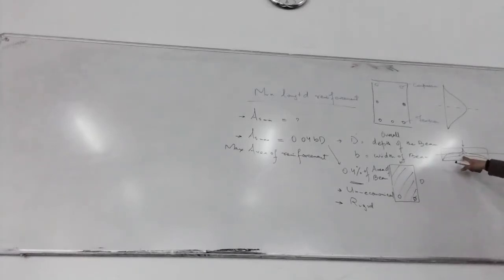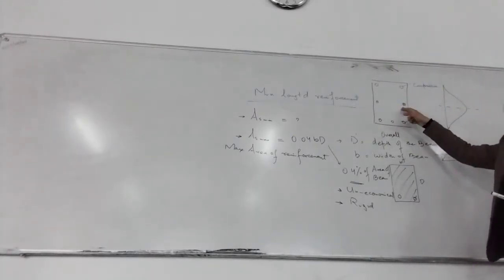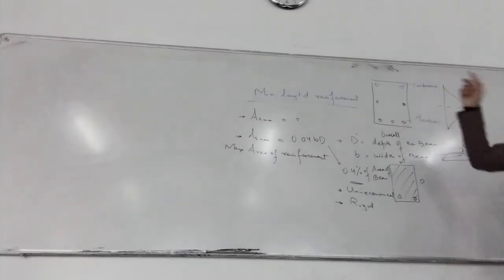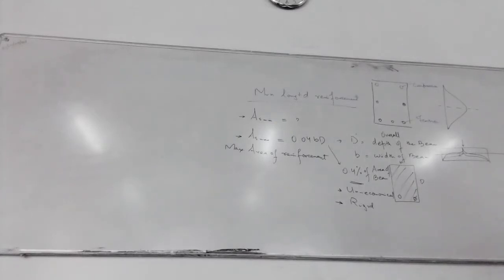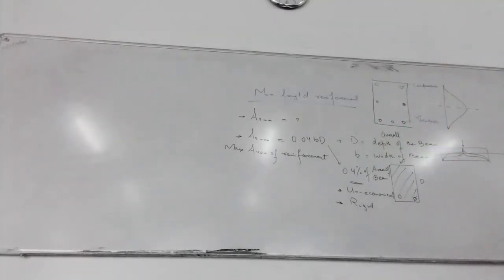The shear plane at the center has the maximum shear forces. For beams getting deeper and deeper, you have more and more shear forces. Then you need to provide the side reinforcement, and this side reinforcement prevents the shear failure at the center of the section. So the purpose of this side reinforcement is to prevent shear failure in deep beams.